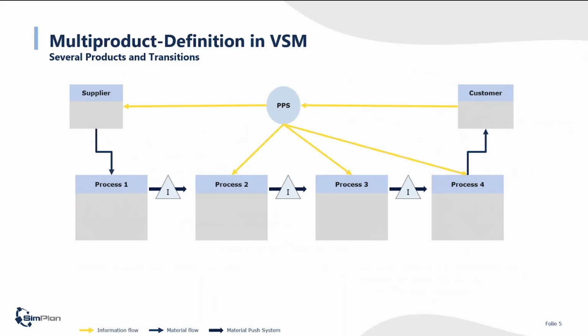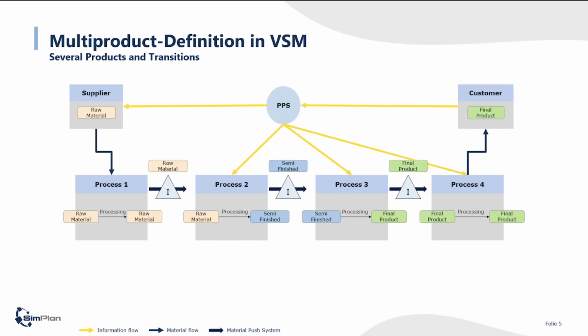Another important point why simulation might make sense in a value stream analysis is that normally value stream is just interpreting a product family, meaning you collect 70-80% of products going over the same sequence of machines, and then this product family is assigned to every station with a cycle time which is an average. It could be a weighted average or just an average based on parts.